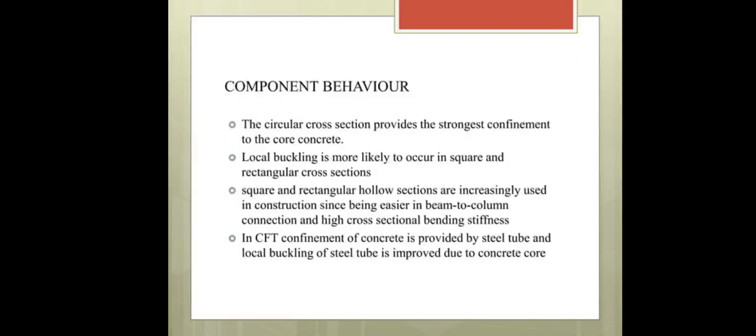We will be discussing the component behavior of the CFT. As we have discussed earlier, CFT are of many types, but among those, circular CFT is more reliable and used widely amongst all of these because local buckling is likely to occur in square and rectangular cross sections.